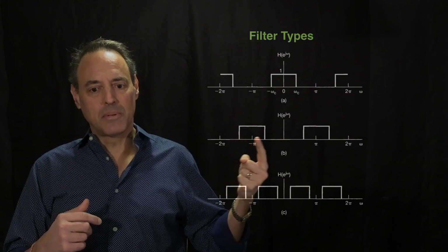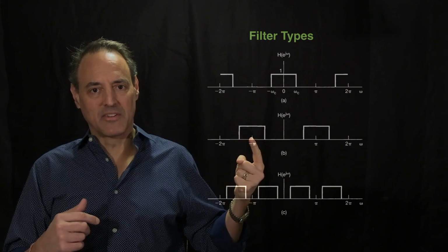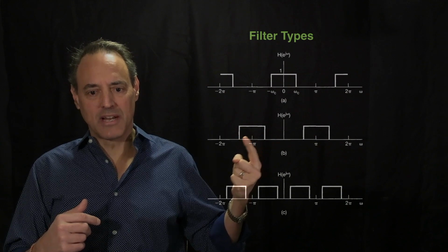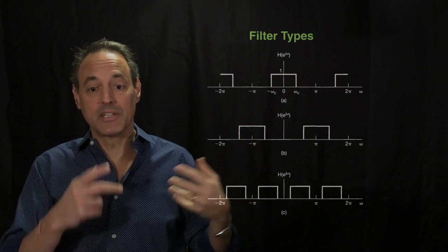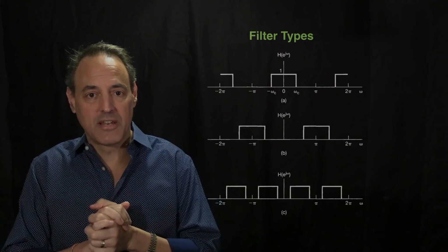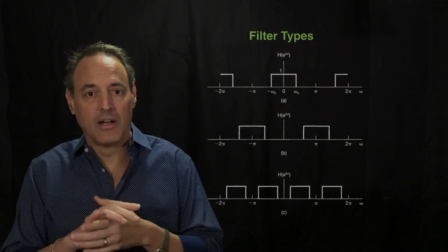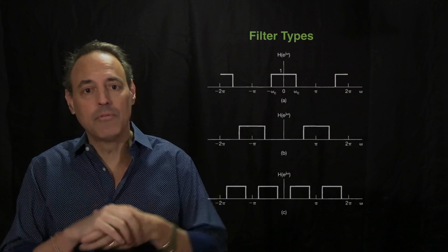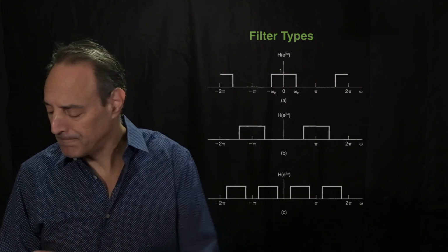You typically would never do a bandpass like this because it has some very undesirable properties if we look at the Fourier transform of what happened on the signal. And so you can design very sophisticated filters that have very nice properties even when you do bandpass filtering.